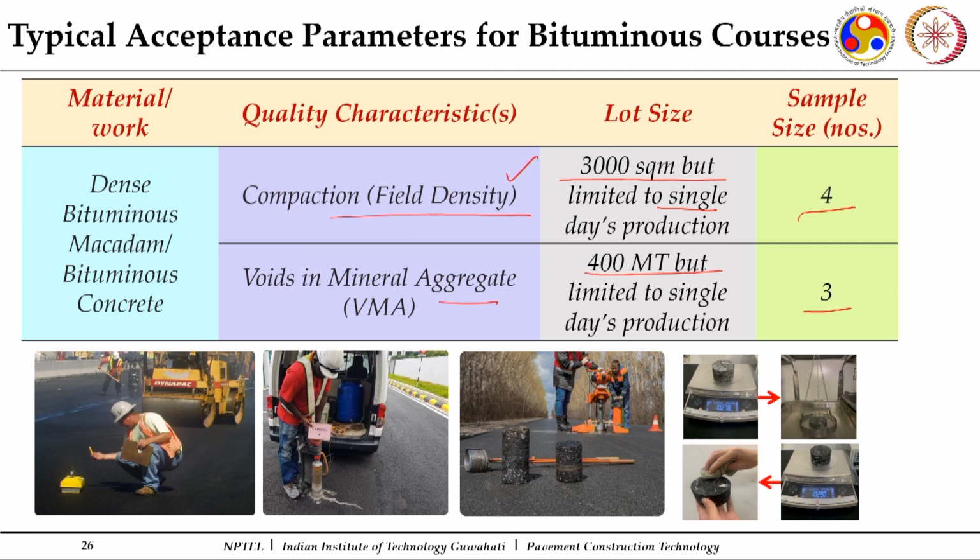So, the most important thing is that we are able to monitor the variability through control charts, and then we should realize that definitely a little amount of variability is going to exist. So, we can work out in terms of the percentage within limits, and then on the basis of this we can judge the quality of these mixes. So, this is all about the aspects related to the quality control of bituminous mixes.